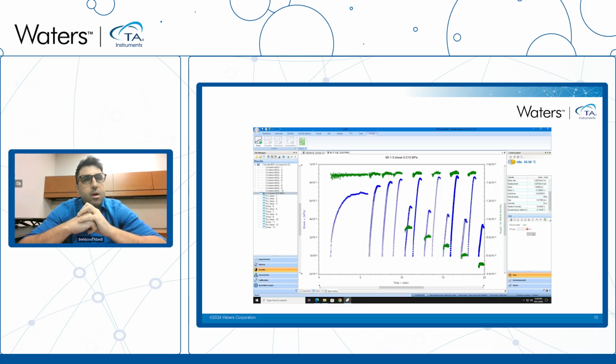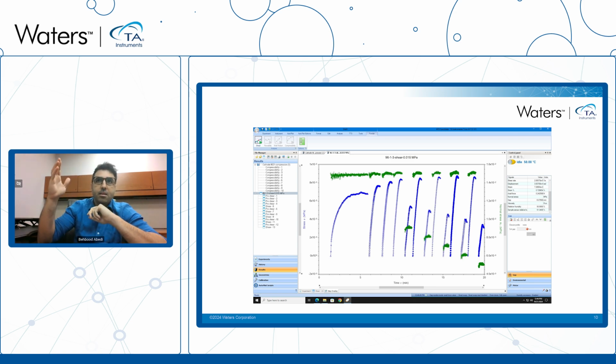Actually, you guys that use rheometers have seen it. When you do a constant shear rate test, for example, for a thixotropic material, you have a kind of straight line with some slope, which is the elastic response. Then you have a viscoelastic response, which is kind of a hump, where your yield point is. Then you get a stress relaxation. Now for this test, if you want to repeat that yield point, it's very important that your initial condition is the same. We have the same thing here.